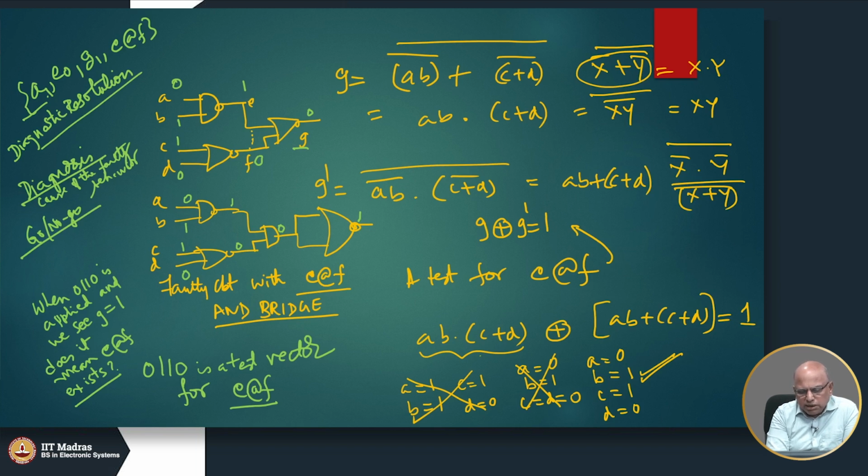Initially, we want to eliminate as many faults as we can through testing, and then finally, in order to diagnose, we can try to use those methods where we uncap the package, and then use acids to expose the layout, and look under the microscope and see where exactly the problem could be.